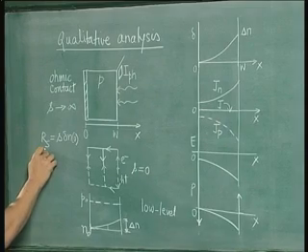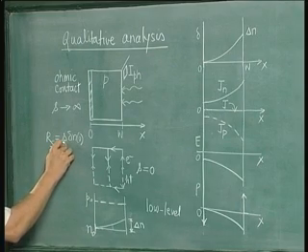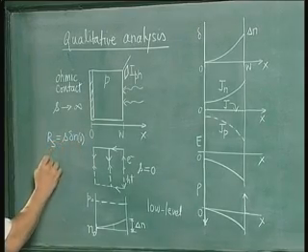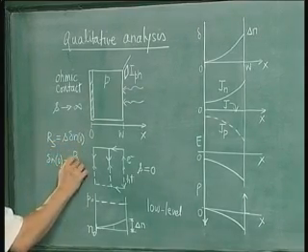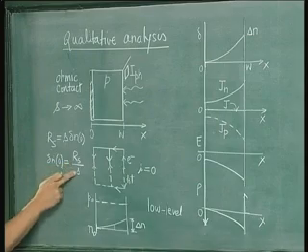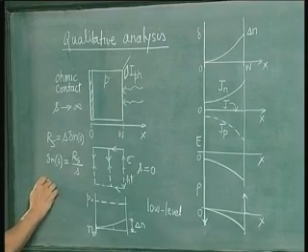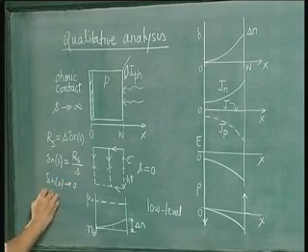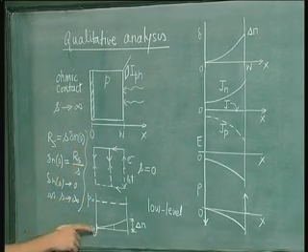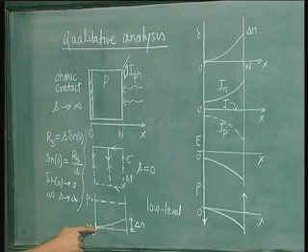This is the equation for surface recombination. Now surface recombination rate has to be finite, no matter what your S is, that is the surface recombination velocity. So we can write delta n 0 in terms of Rs and S as delta n 0 is equal to the surface recombination rate divided by S. Since Rs is finite, it has to be finite, but S is tending to infinity because it is an ohmic contact. This means that the excess carrier concentration tends to 0. So delta n tends to 0 as S tends to infinity. Okay. So this is the reason why excess carrier concentration is 0 at an ohmic contact. So this is the distribution of minority carriers as a function of distance.